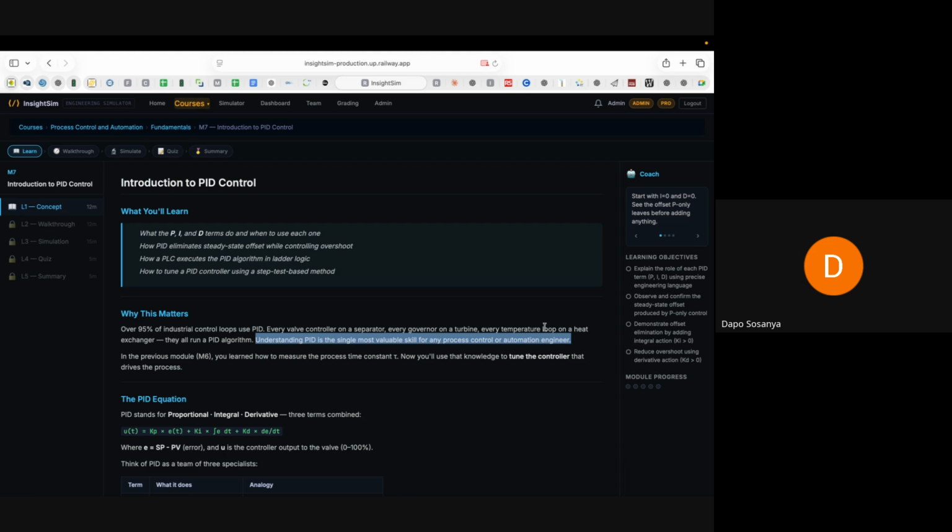I took it to the University of Ibadan, to the food technology department or food science department, and they ran a temperature profile to understand the heat, the point at which that product gets burnt. So I got that range and I set up a temperature control loop for them using that range as my set point. And the system worked.